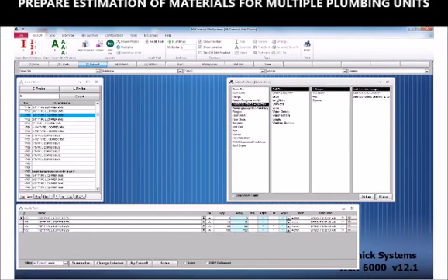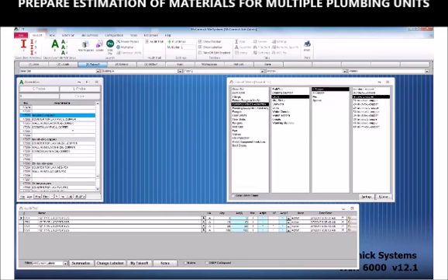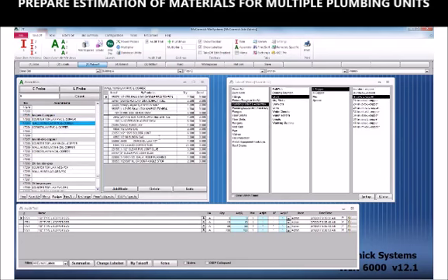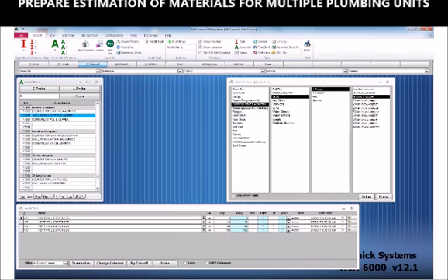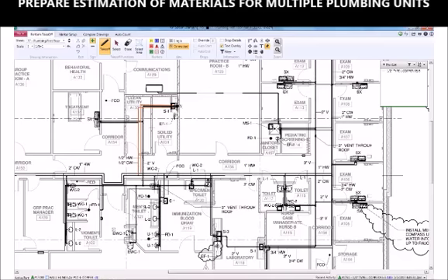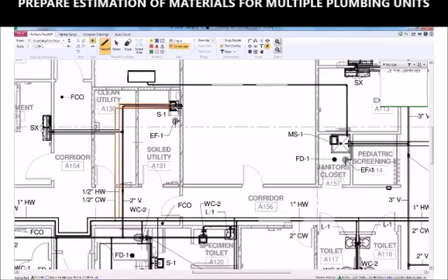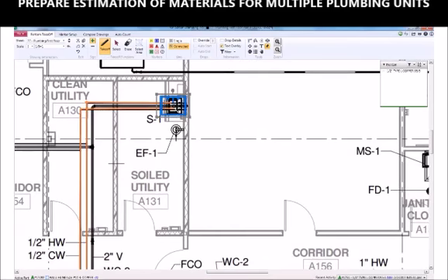Let's go ahead and grab a lav. We're gonna pick L copper coming in, and we want PVC going out. Let's go wall hung. Again, you can see all of the parts and pieces we need to install that. And our OSE Pro specs show it's a blue lav. Again, all we're gonna do is place that lav right onto our PDF, and the program automatically counts it.